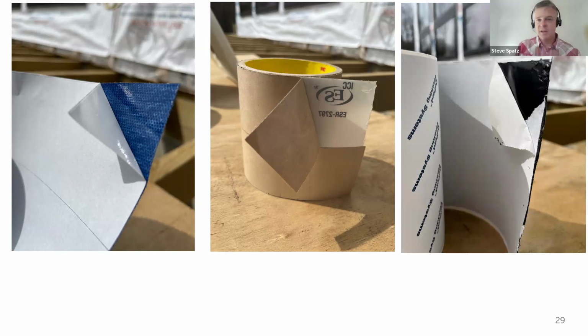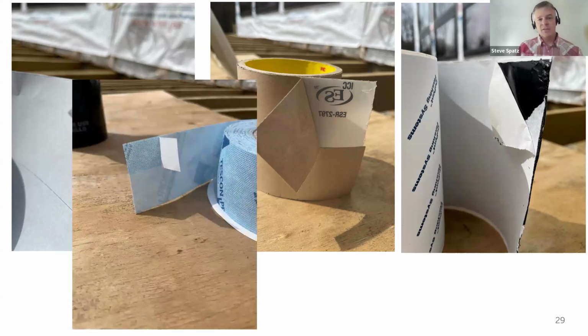And then beyond those types of tapes, there's a lot of different products that are available for window flashings, butyl and urethane embedded tapes. You have to be careful about compatibility with substrates with some of these. They can break down vinyl or other materials that would be commonly in place with windows, window flanges. Backings of the tape from manufacturers as well ease the installation and the intended use of these tapes. So split backings on tapes can be used to seal irregular joints, inside corners, other parts of a building where having that flexibility of folding the tape into a joint can be very beneficial.